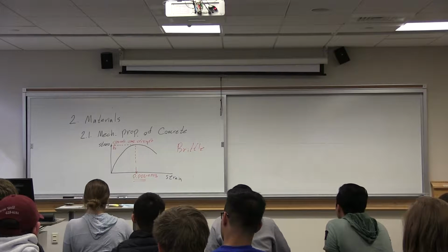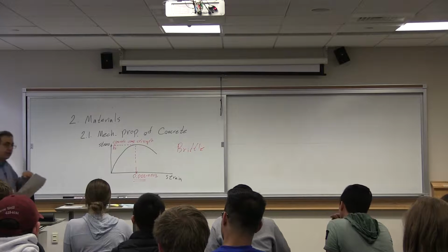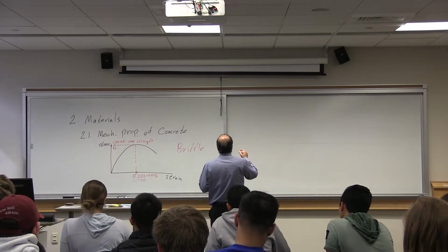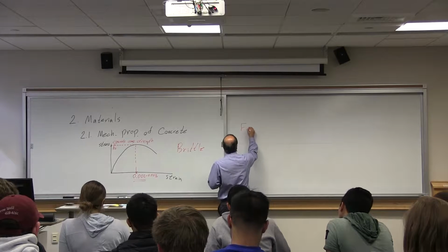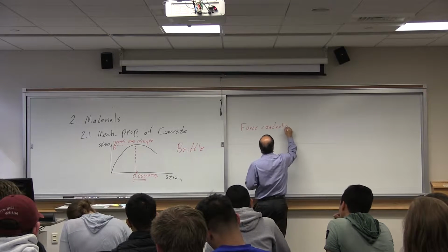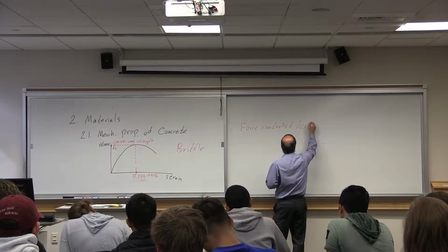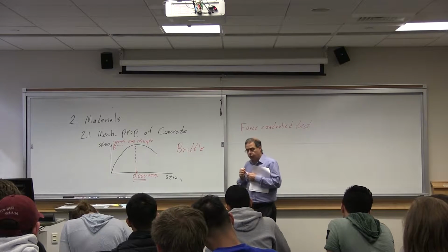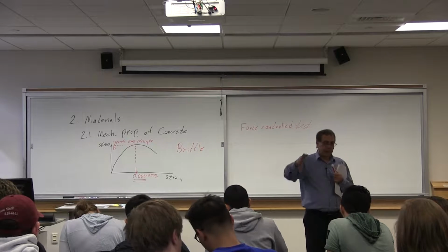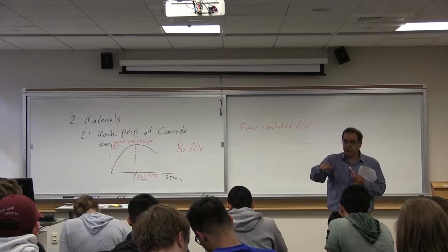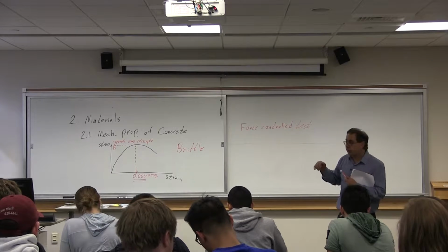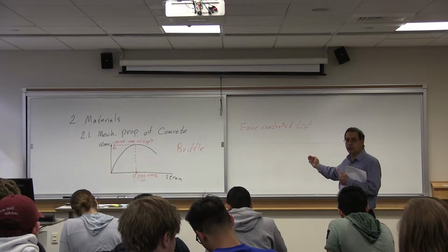Practically it's impossible. What you do instead, you don't do a so-called force controlled test. What does it mean, force control test? That means you are controlling the force. Apply 10 kips, apply 20 kips, apply 25 kips. That's force control. If you do a force control test, you cannot get this one.